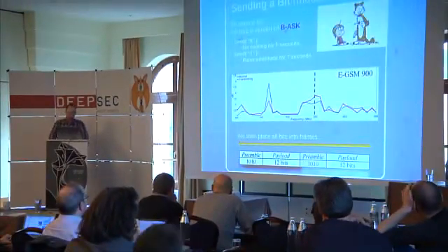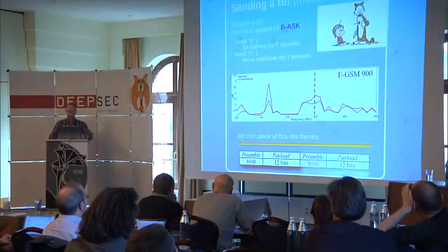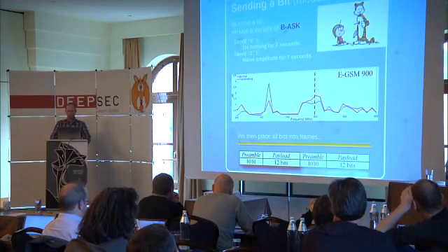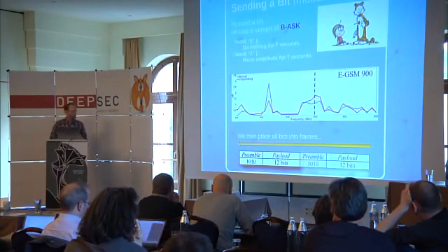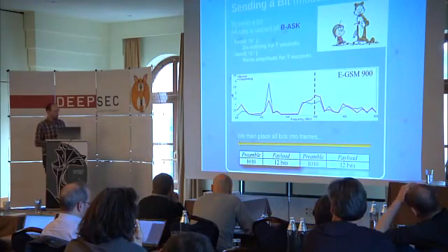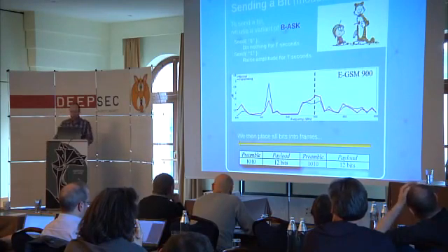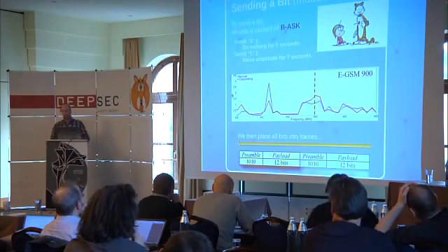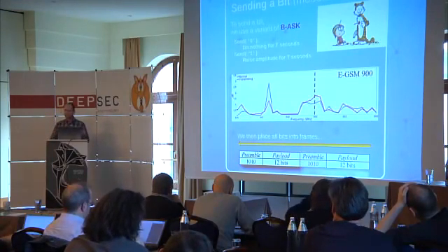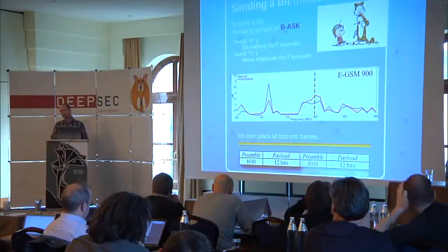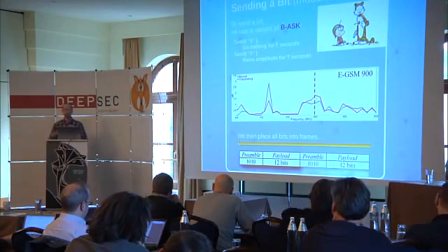So how do we send a bit? To send a 0, we do nothing for t seconds, and to send a 1, we cause a large transfer for t seconds. And once again, we put this in a frame. Every 12 bits, we put a preamble in front of it for a few reasons. One, synchronization. Because we're talking about wireless communication, the receiver can move away from the transmitter, so we have to adjust thresholds and so on.